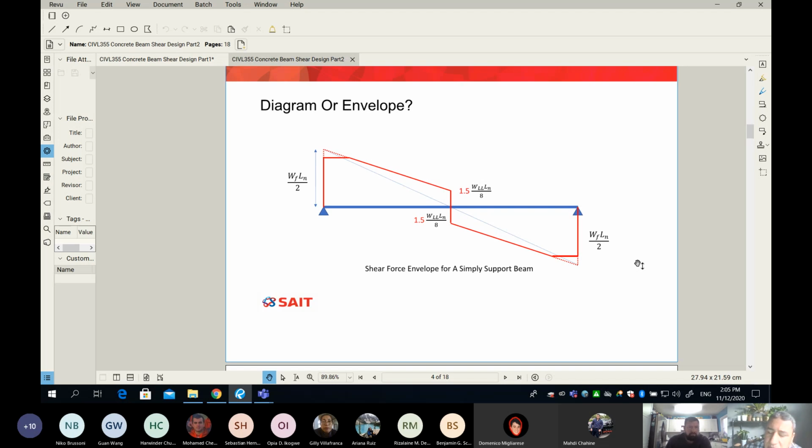Now, guys, I know some of you already said, okay, you know what? If I have a shear force of, let's say, 500 that I want to resist, and concrete can do only 100, then why don't you take the 400 and simply find the spacing between the stirrups? But the thing is, this Vf, the force that I'm trying to resist, is not constant. It is changing along the beam center line.